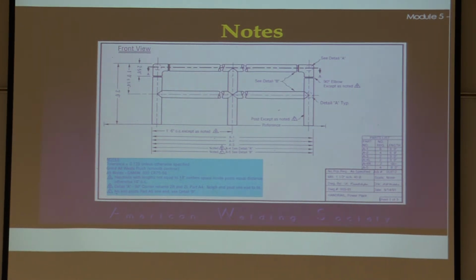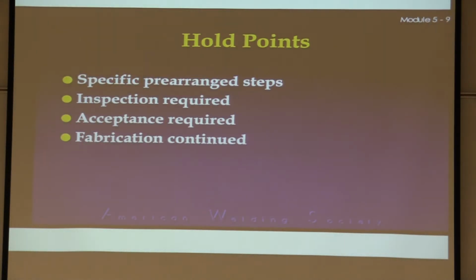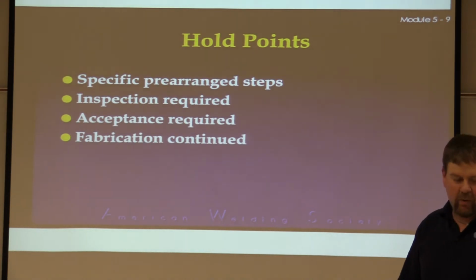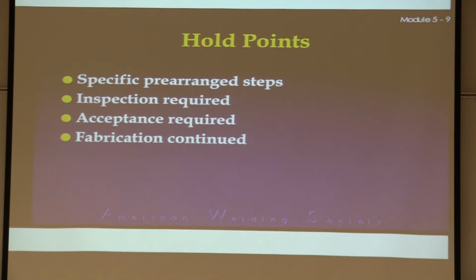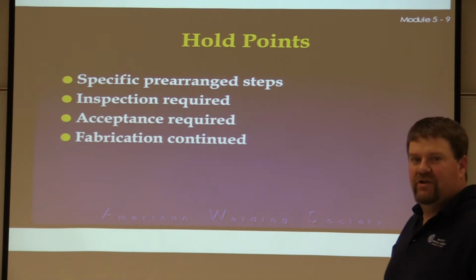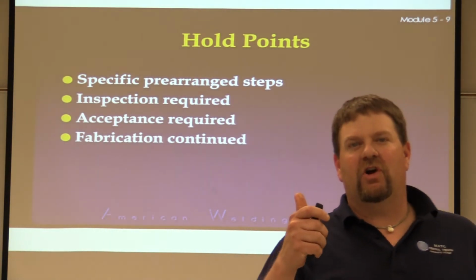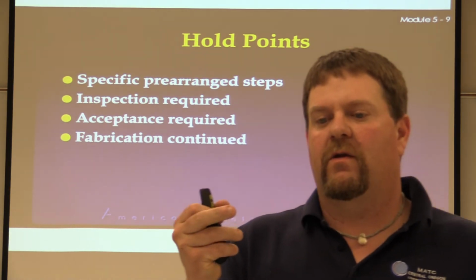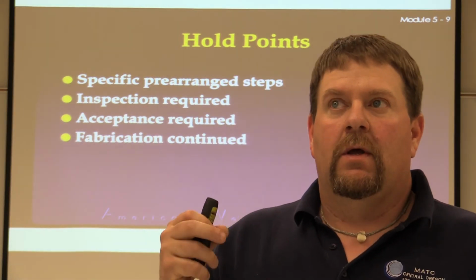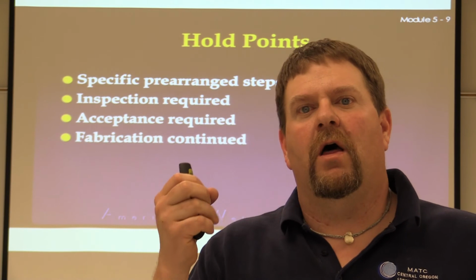Okay, page 5-4. We start talking a little bit about some of the hold points, okay? Page 5-4, left-hand column. First paragraph down, well, the first sentence in there actually starts out, the weld inspector should be aware of this before starting any welding whatsoever. So just remember, you're not just in charge of the welding, but the cutting process, how we got to it, especially in certain alloys. Was it air arc, was it saw cut, was it not?